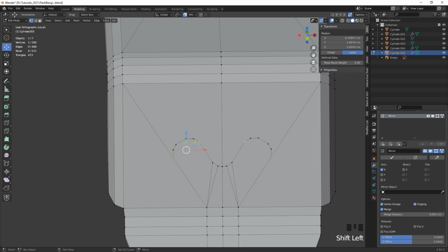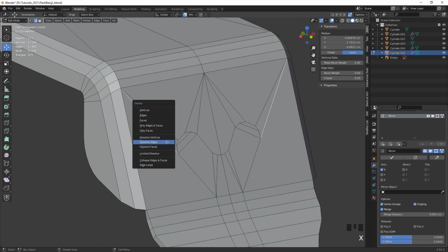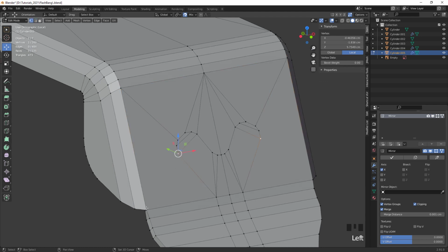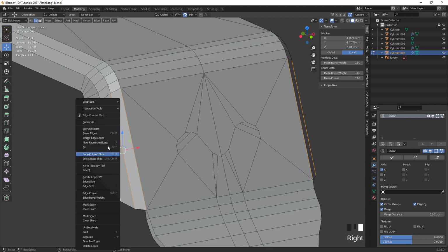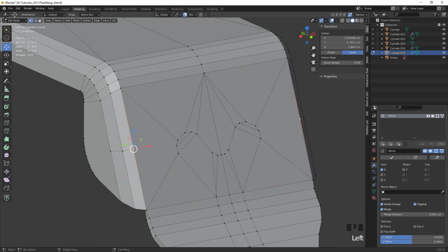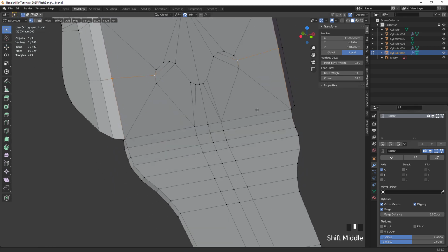I'm gonna go ahead, make some vertex connections here with our edge. And also here to the upper part, so that Blender knows how to triangulate that. And we might add more later. I'm actually gonna dissolve that one here, and I wanna use a connection down here. And then I'm gonna select these edges here with Shift, and I wanna subdivide it so that we have an extra edge loop there, because later we're gonna have a Boolean hole in there and we connect it to this.